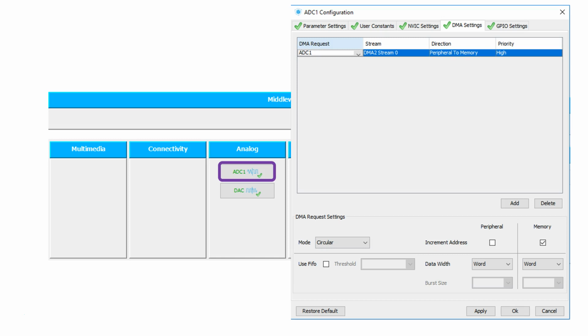However, with circular mode, once it gets to the end, the DMA will go back and start at the top, repeatedly filling up the array. So basically, to summarize, the circular mode allows the processor to reuse the ADC result array, which I called ADC_val just now, repeatedly during each sequence of the ADC conversion, so that we're not overrunning the memory that we had set.